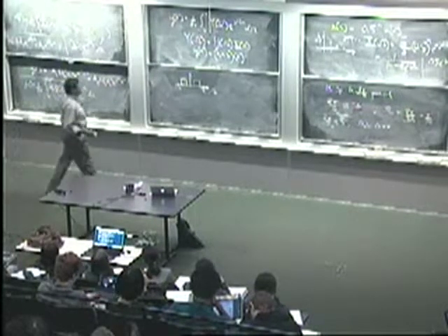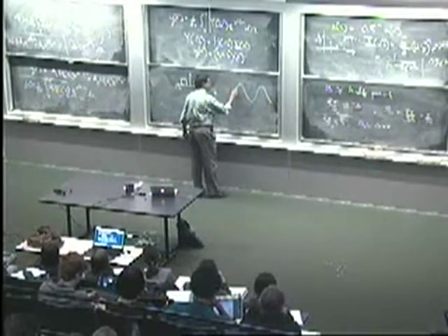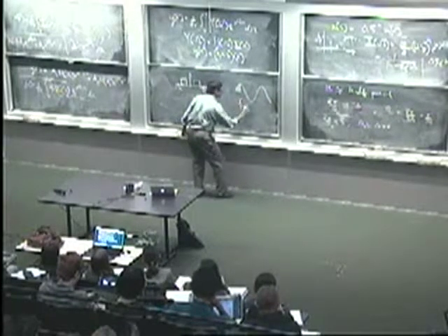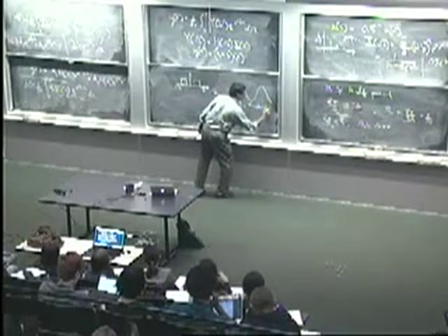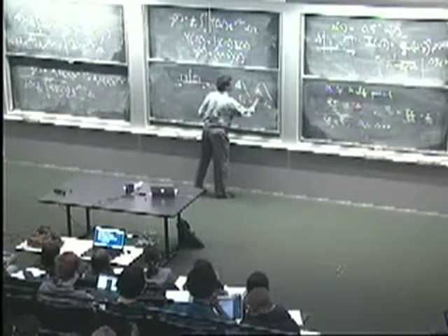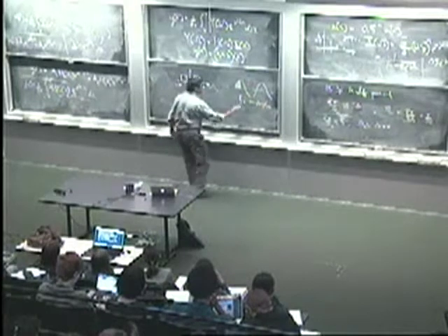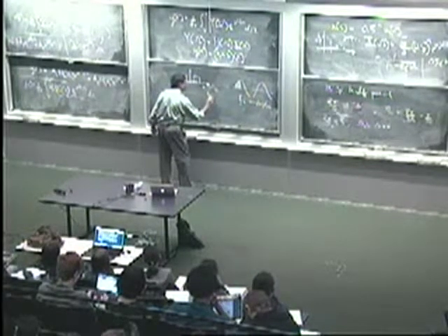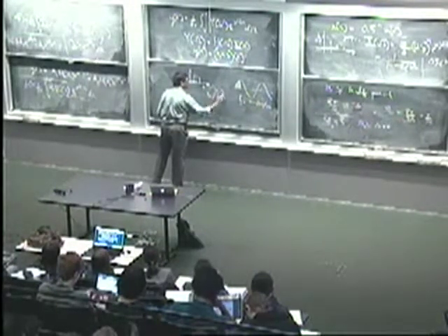So you actually need a way to go from an underlying continuous time signal that's sampled at a particular sampling rate, let's say f of s samples per second, to a corresponding omega for the underlying discrete time sequence. Okay? So the question is, how does fs map to omega? And I had a slide last time. I haven't gone through it in detail. Maybe we'll have you work through it on a homework problem, but this is actually the mapping.